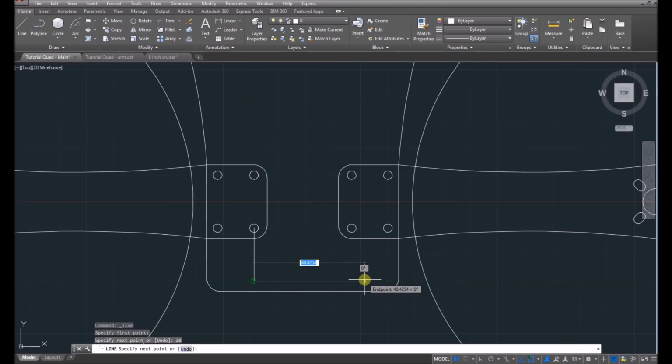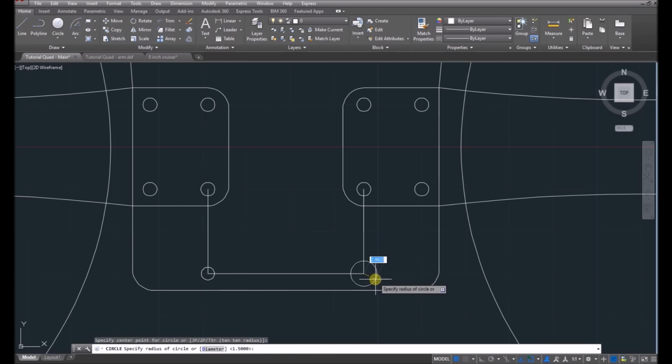Now, disclaimer, this is not 100% thought out. I'm just doing it for the purpose of the tutorial. Okay. So, let's just say I want a strap along here, and then maybe have one behind there as well. What I would do is mark it out like that. For straps, I always go 1.5mm diameter, because that's enough to fit a strap. 1.5mm diameter. Grab the line and go like that.